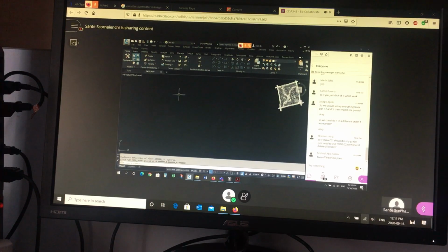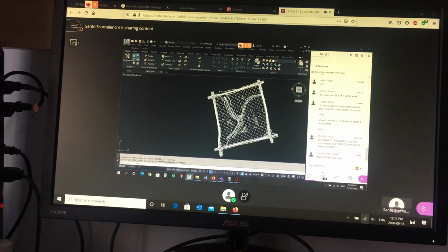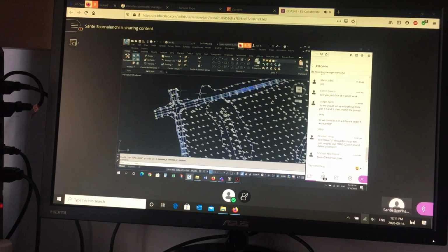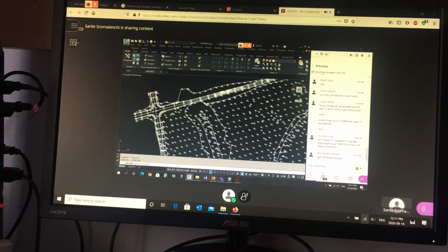So do not insert it first. You have to fix that setting in the other drawing first. Make sure that the other drawing is also in meters. And then when you bring it in, it should fall right into place. And if you didn't explode it before, you can explode it now. So now you'll see it's connected all the dots, or most of them.